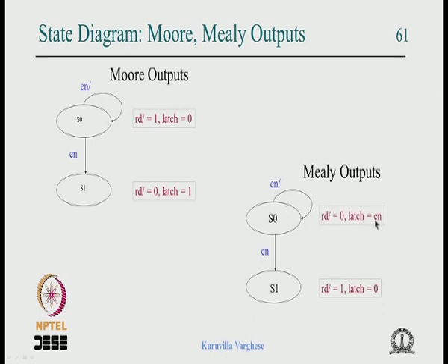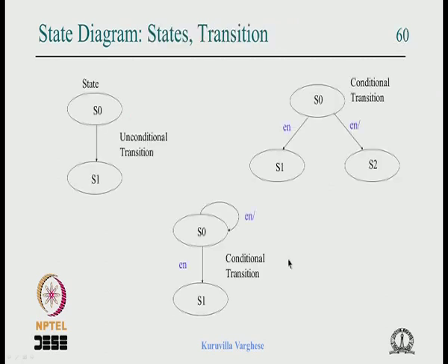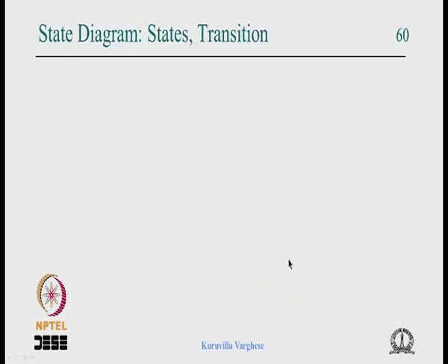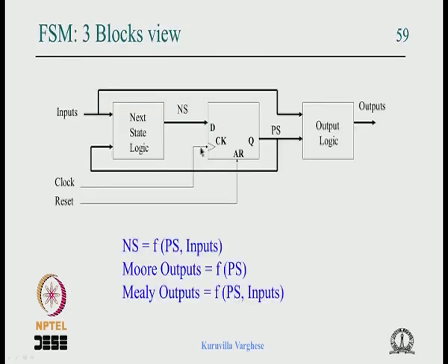So that happens in this state before the state changes, and this means in the next clock the transition happens, and you know that the enable has to be set up much before for the transition to happen, because the enable has to come some time before, by the setup time and the logic delay, then only the transition can happen.